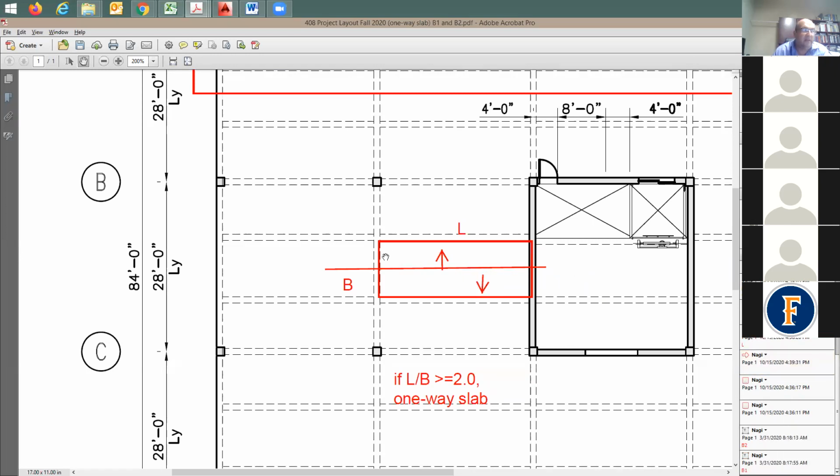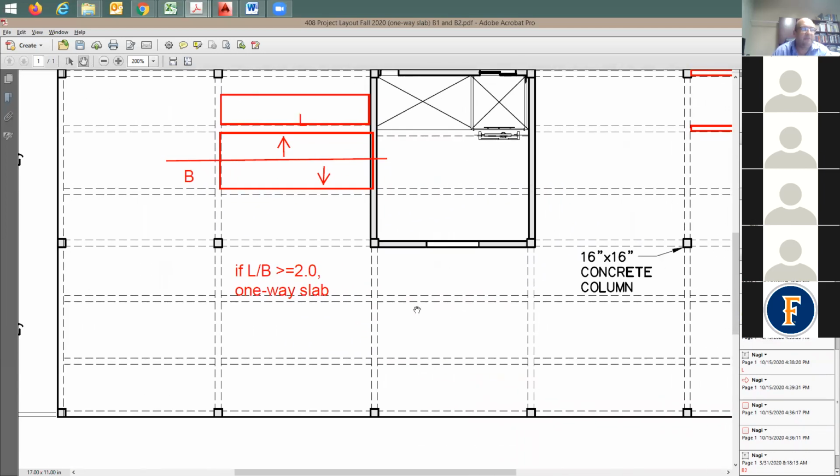Is there anything that is going directly to the girder? I'm going to say no. In one-way slab, we assume that this beam here supports this piece of the concrete slab and a similar piece from the other side, like in here. If I go to any other beam, how about this beam here? How much does it support? This beam supports this part of the slab and a similar part from the other side. So it supports this tributary area of the concrete slab.